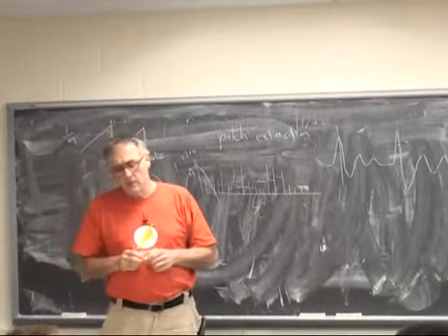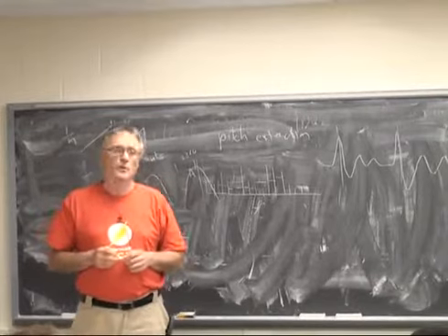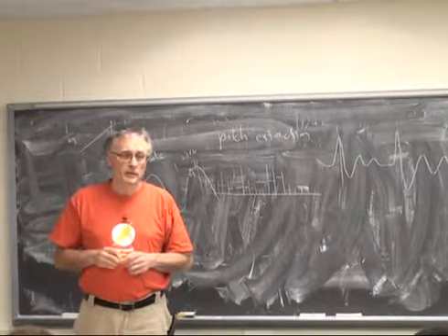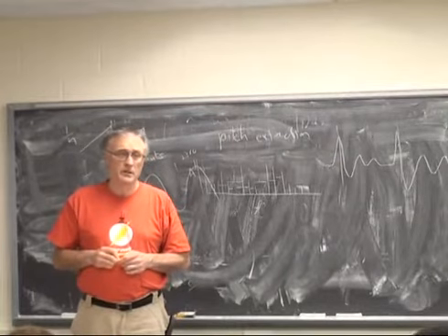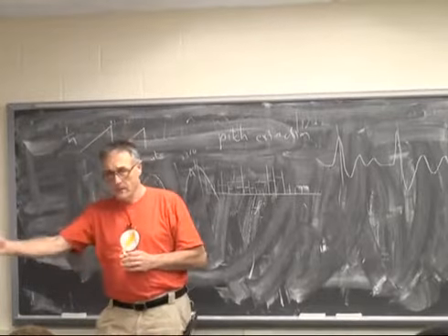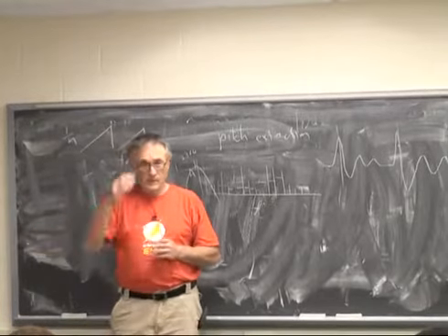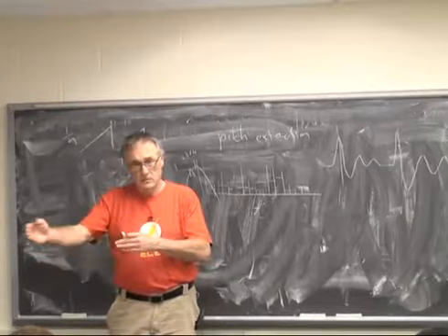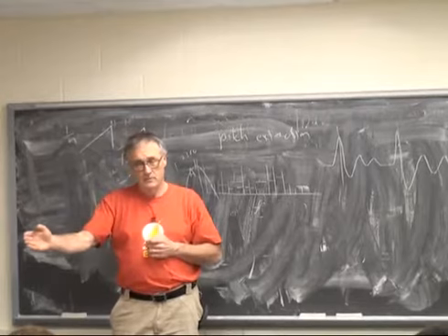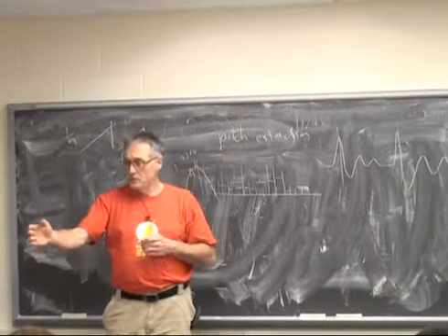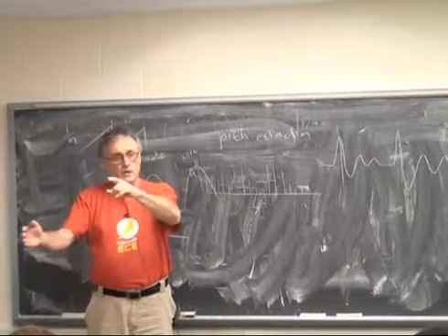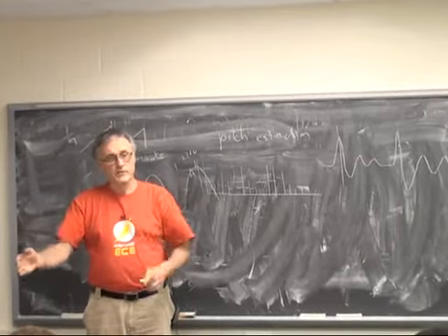Yeah, you can use acceleration to calculate position, but it doesn't work very well, because it requires a double integration, which, with noise, tends to accumulate errors with time.